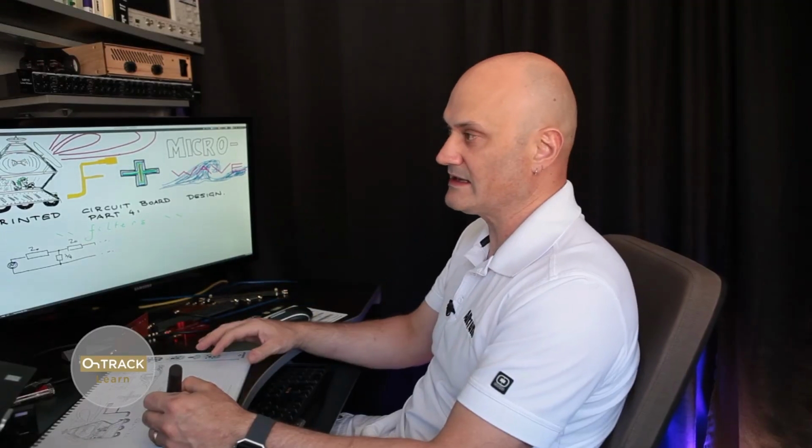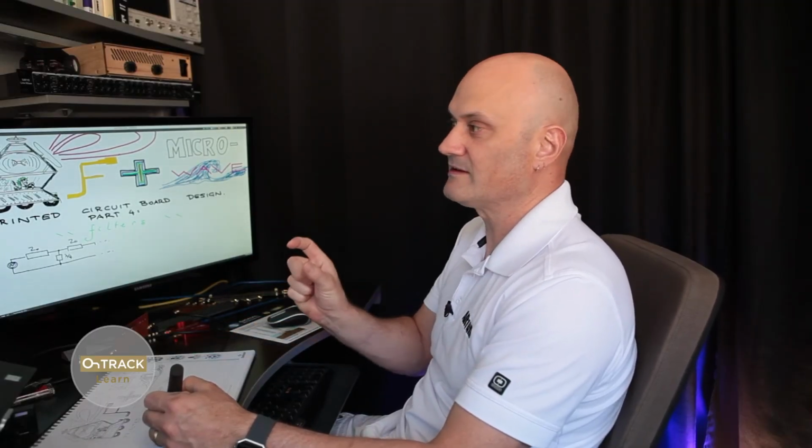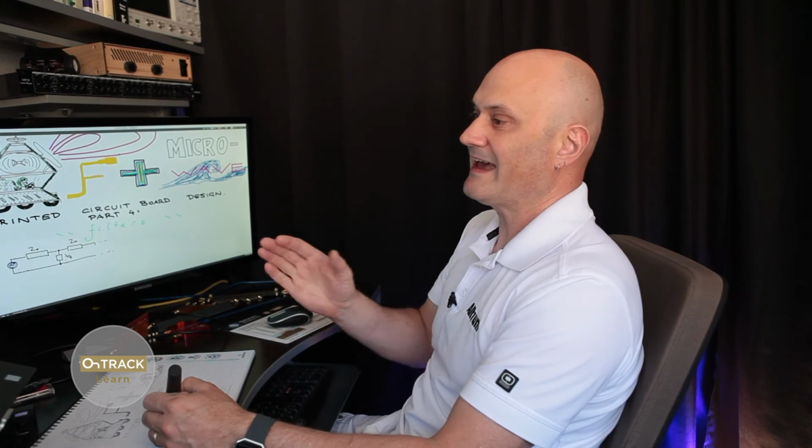And similarly, an open circuit stub will appear as a dead short at a quarter wavelength. So there's a sort of duality here between transmission line segments on the PCB and other elements, namely inductance and capacitance. So how can we use that to make filters?